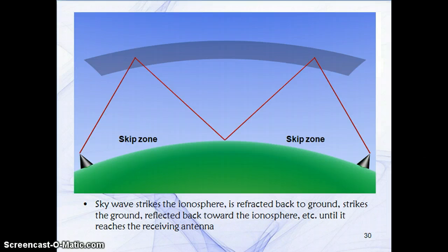Ions in the upper Earth's atmosphere are formed when ultraviolet radiation and other radiation from the sun knocks electrons from the gas atoms. Much short and long distance communication below 30 megahertz depends on bending or refraction of waves in the ionosphere. The most common is in the 20 to 30 megahertz range. Communication distances of 2,500 miles are possible with one skip off of the ionosphere. The skip propagation has both minimum and maximum ranges. The area between